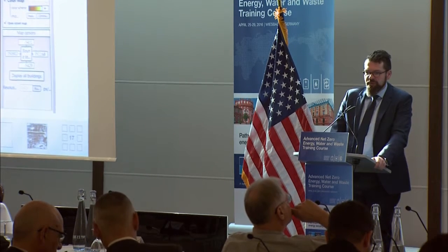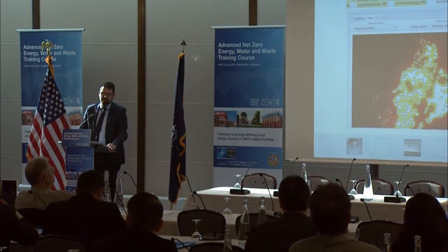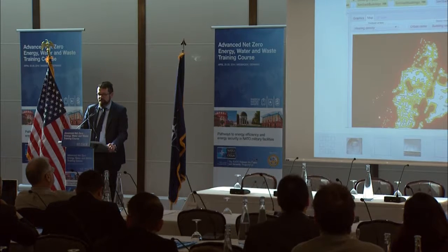So you can also do this with a level of detail 3 GIS model, which means you have a laser scanning of all the buildings, and you can calculate automatically, including some kind of utilizations and occupations and building physics, the heat load for each single building. Again, you can come up with a heat map which shows you in these highlighted areas where it probably makes sense to figure out if a central heating system will make sense, and it probably will not make much sense if you go to these low density areas.